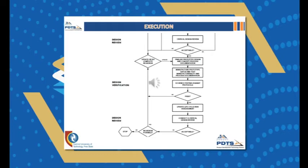Work instructions required for process control should be defined and documented. The quality requirements for the product should be defined and adopted from published standards and guidelines. Important parameters such as clearance, tolerances, special material, relevant standards and specifications, etc. must be defined to ensure that all the quality requirements needed for the reliable functioning of the prototype are specified.